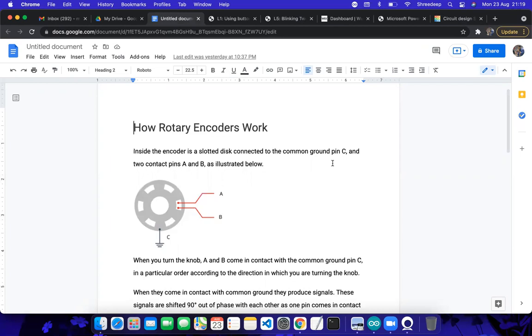The microcontroller is basically reading inputs from two points, right? The clock and the DT. So in that way it is a sensor, but at the same time it provides some mechanism internally, which is the actuator, right? So the rotary encoder, you can say, is also a shaft encoder, which converts its angular rotational displacement into an analog or digital voltage. Right now we are dealing with all digital voltages.